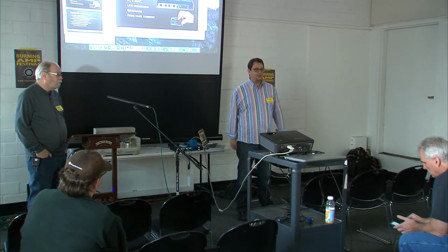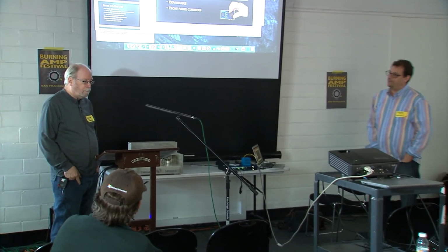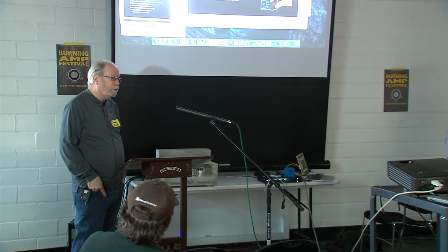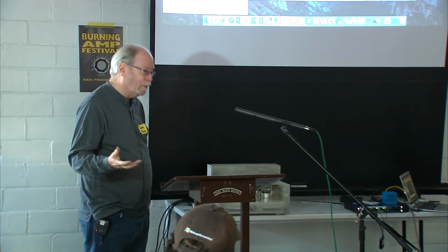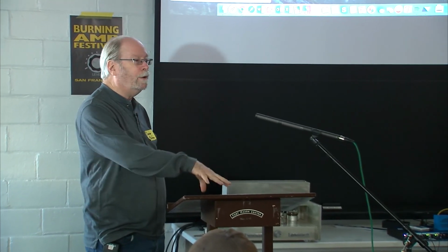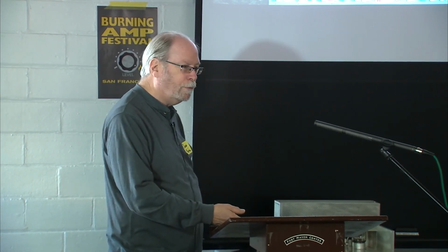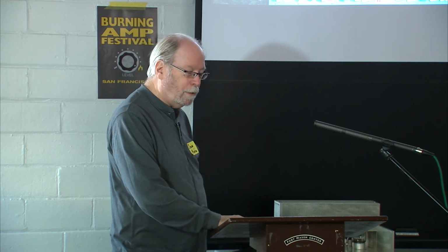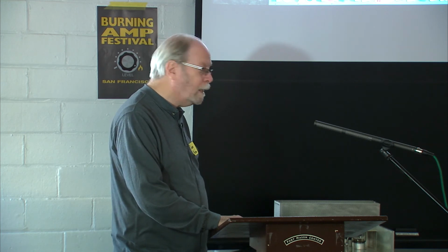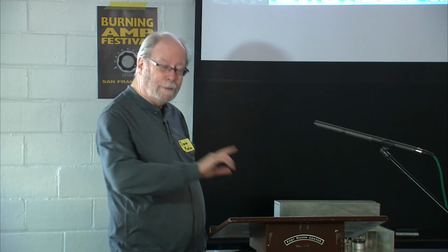Yeah. During Class D with older analyzers. Oh yeah, that's a very important thing to keep in mind, because they will have almost full scale at 200 kilohertz to 500 kilohertz on the output. You have two issues with them. One, this will potentially limit the input, especially if it's an older unit using a 5534 op amp, which doesn't do well under those conditions. The other classic problem with one of those is how many FM stations it knocks out. And depending upon how loud you're playing, it's a different station.